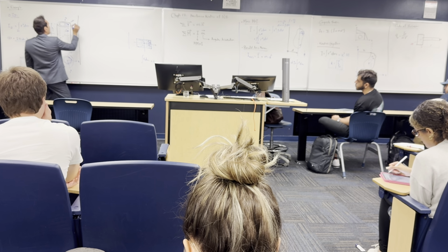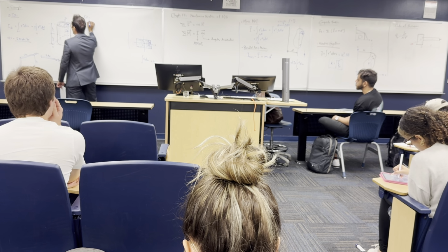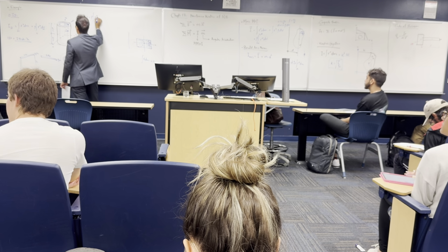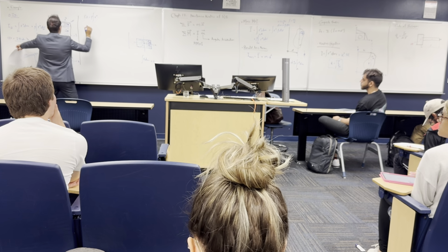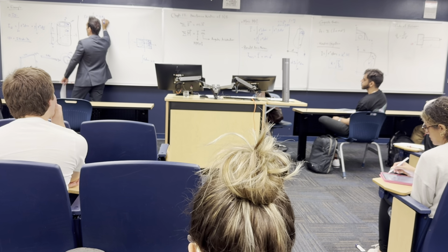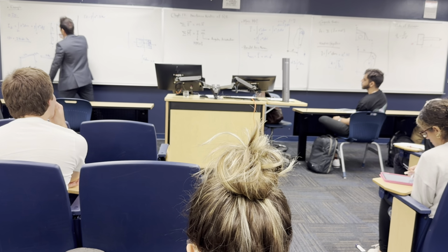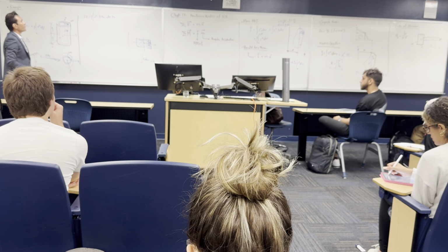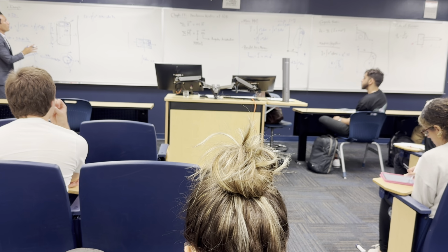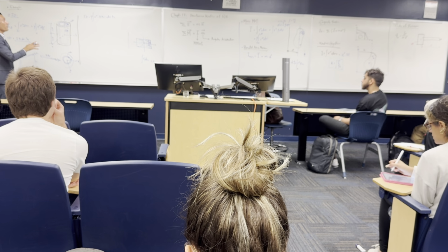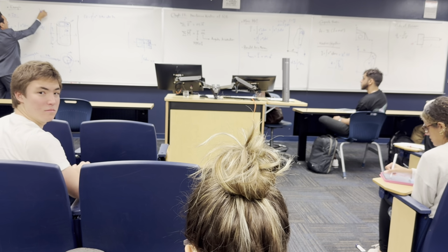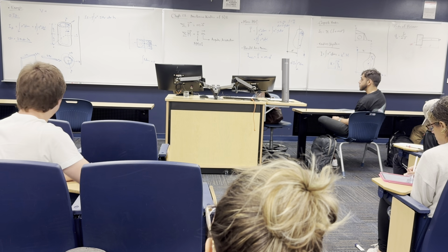So here I can write that Iz is equal to the integration, I have the rho outside, rho r squared multiplied by dV, which is 2 pi r dr multiplied by h. But you know what? There's lots of variables here, but I can decrease these variables knowing the volume. Can you guys tell me what is the total volume of this cylinder? The volume of the cylinder.